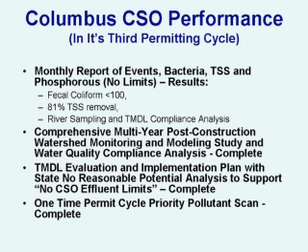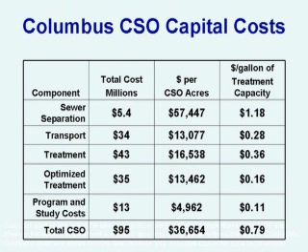The river sampling is required for every event that they monitor. The river sampling is upstream and downstream of the city, and TMDL compliance analysis, like a mass budget, is conducted for that sampling, where you take the upstream sample plus the samples from the CSO facilities plus samples from the wastewater treatment plant discharges plus a calibrated model output from the tributaries. You add all those up and compare it to the downstream measured values, and that's what is reported in Columbus.